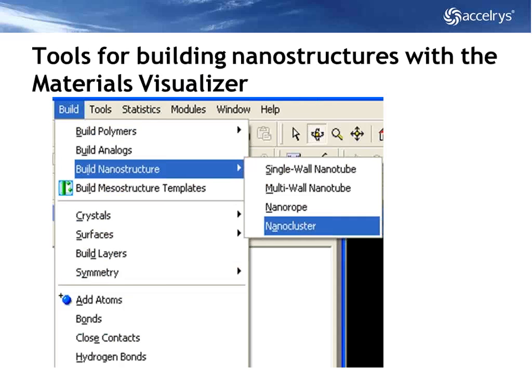Nanostructures, well, we have a nanostructure series of builders, so this is appropriate to the Institute and I think a number of people in the audience. This nanostructure builder is really easy. It's sort of simple. You can build nanotubes and nanoropes, just boron nitride or carbon-based systems by defining the translational vectors as you map out of the graphene layer.